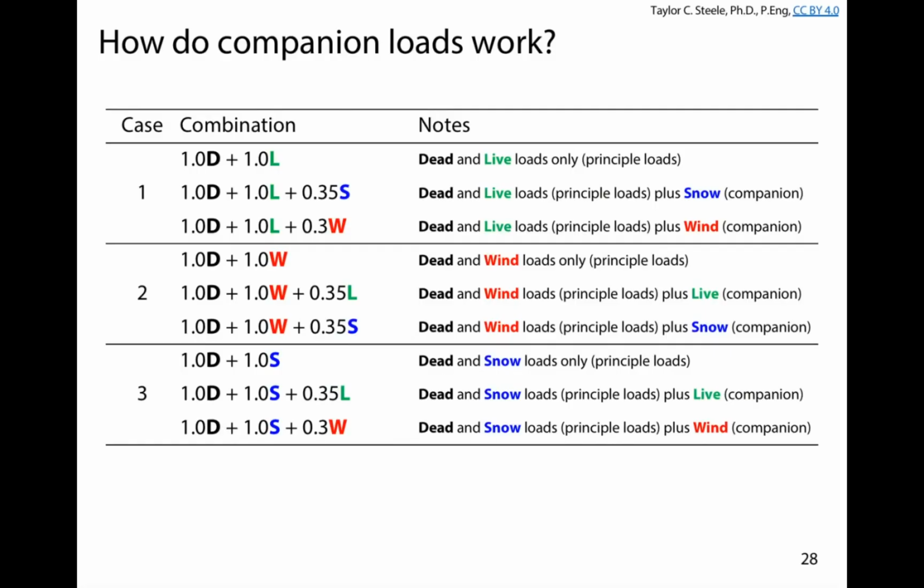And so primarily how this is going to play out for us is in terms of maximum deflections, either lateral or vertical. Okay, so trusses will get pushed to the right, so the building will get pushed to the right. We don't want the pretty stuff on the outside to crack and fall off, so we're going to put a limit on that deflection. We don't want our beams to sag down too much under the snow or live load, otherwise the floor is going to crack. That's not something we want to have to deal with all the time, but these things are more acceptable to us than failure of a structural member.